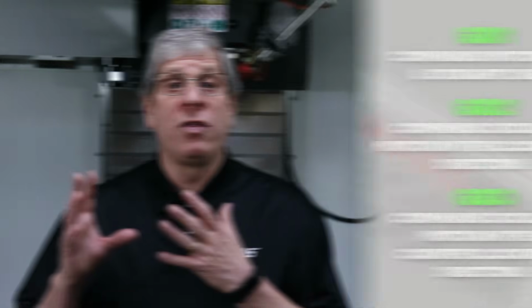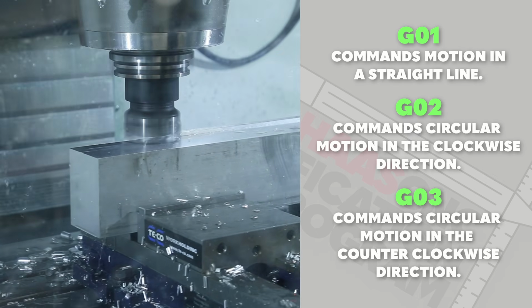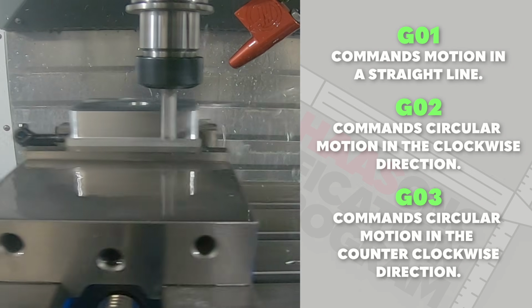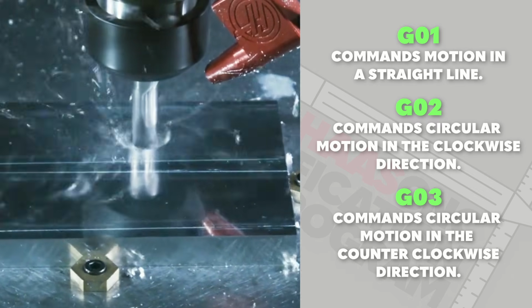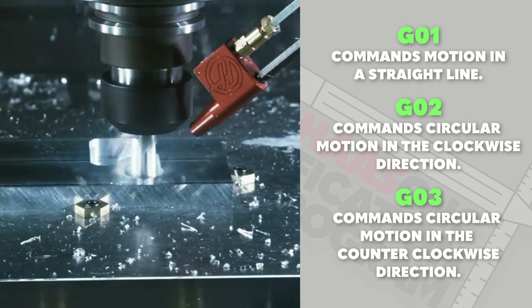In a simple sense, most of the motions that a CNC machine makes are based on 3 G codes. G01, which is motion in a straight line, G02, which defines circular motion in a clockwise direction, and G03, which is circular motion in a counterclockwise direction. The machine is capable of producing extremely complex shapes using just these 3 G codes.